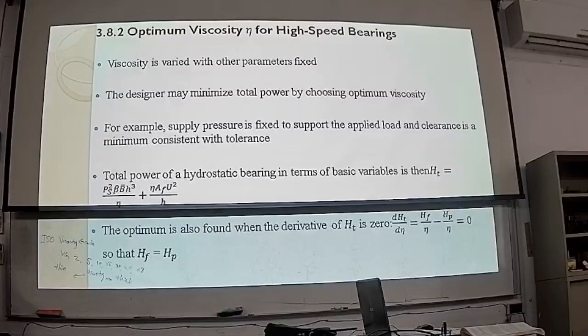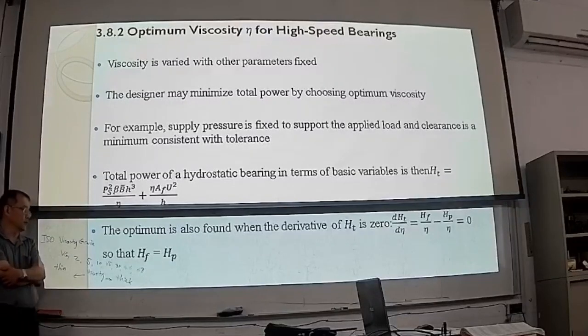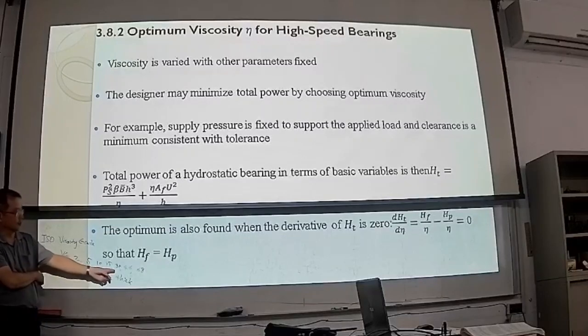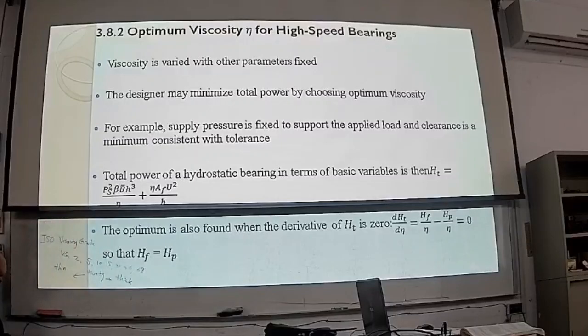So viscosity in this case, okay. If you have a hydrostatic bearing rotating at very high speed, you need to select a small viscosity grade number. If your moving speed is very low and you have a heavy loading for your bearing, then you tend to select a thick viscosity lubricant. Okay.